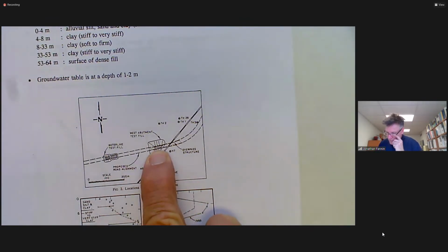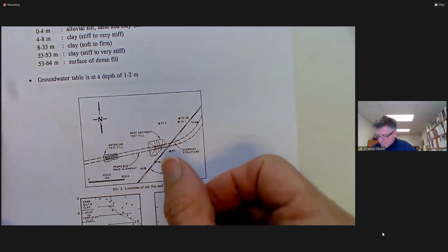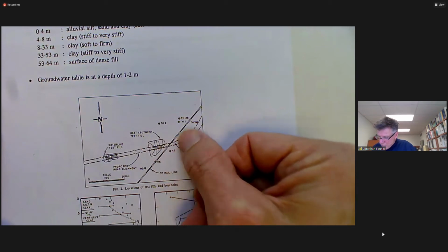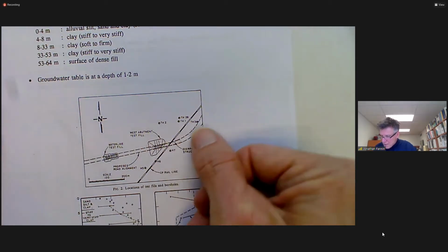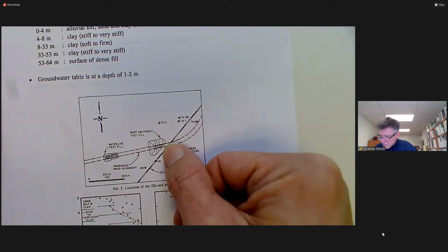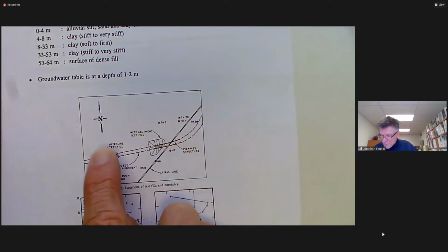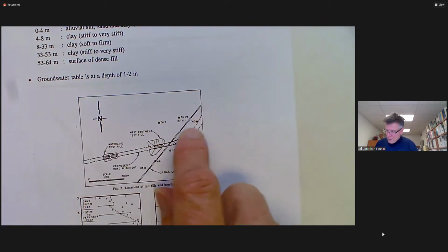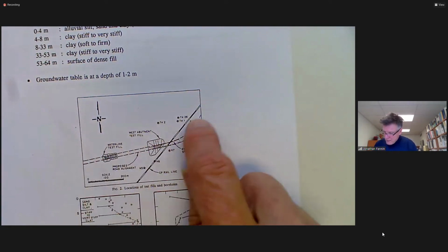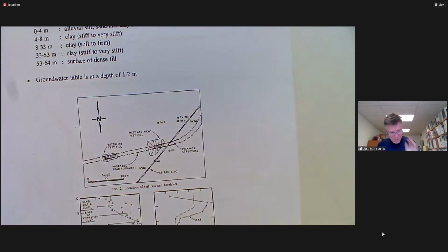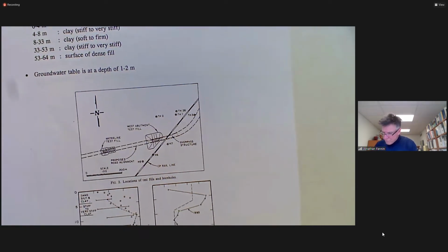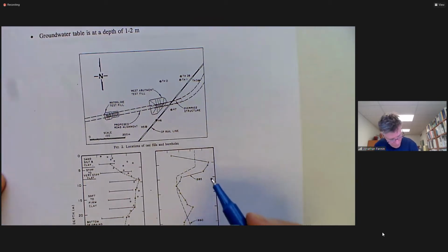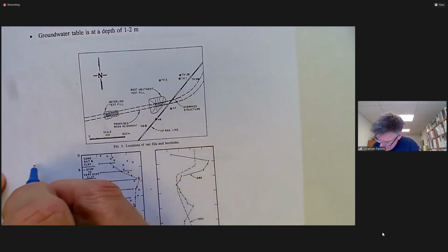The west abutment test fill, so-called because it was going to be abutting a bridge overpass over the CP rail line just on the outskirts of Vernon, and the waterline test fill, which was going over a utility. An embankment was going to be built, and the bypass road then put in. And the ground conditions: the water table was of the order in the upper 2 meters or so.